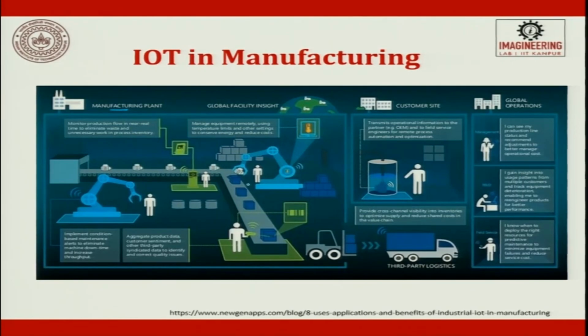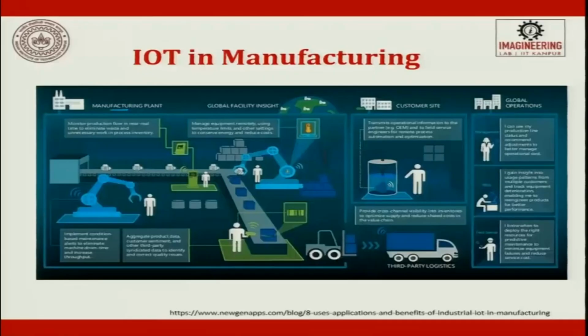So, this is the other thing. Today in air conditioners, they have inverter air conditioners which do not switch on and off after a certain limit. Earlier it used to have a thermostat; the moment the temperature fell below the limit, the complete system switched off. But now they say it will not be a complete switch off, a fan will keep circulating, and once the temperature rises, the motor or the refrigerator will slowly switch on. So, they say it is energy efficient. Here the temperature control limits are set.